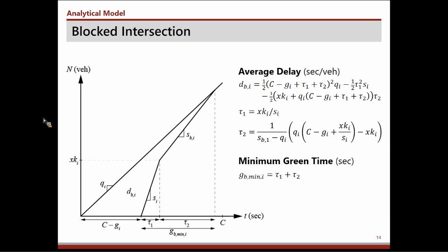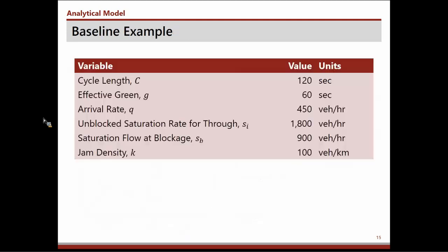Once you've cleared out that queue in front of the truck, vehicles can only get through at the rate that they can get past that truck, and that's that lower rate that you see adding. So in a sense, the course model is giving the most pessimistic view of what the effect of the vehicle on traffic flow is. And this detailed model represents the subtlety, the idea that the location of the vehicle matters, and as you move the vehicle away, it will have an impact on delays.